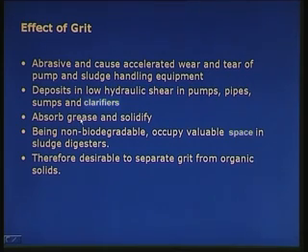On grit the grease is adsorbed, and the grit is definitely non-biodegradable. They are non-biodegradable organics. They cannot be degraded, because bone chips are non-biodegradable, eggshell is non-biodegradable, grit is non-biodegradable, pebble is non-biodegradable.